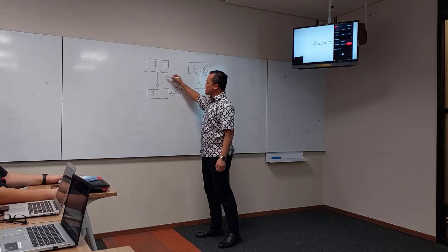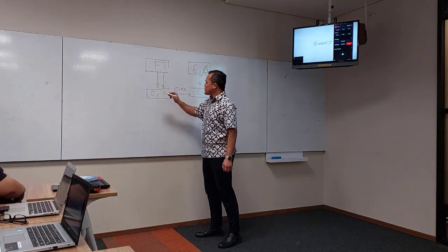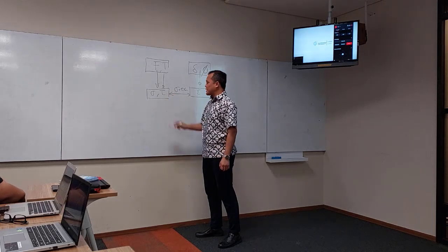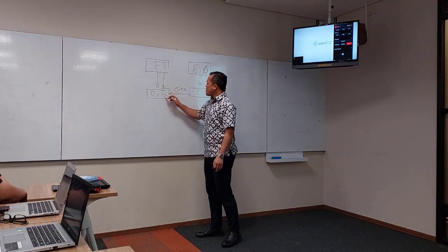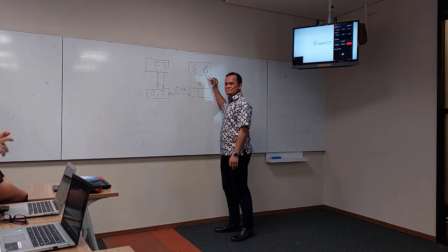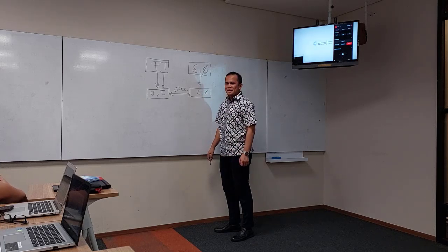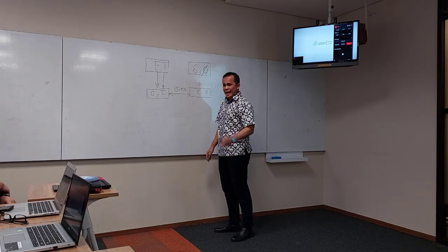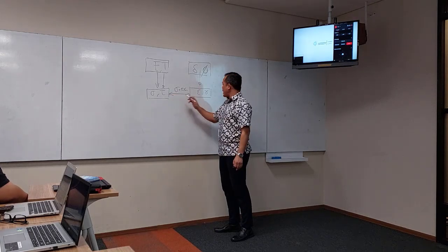Therefore, you convert torsion into stress as well. As a clue, it becomes shear stress, tau. Between tau, this phi also needs to be translated into strain. The strain for torsional movement is gamma, because shearing is gamma. The angle, remember? Okay. So, what relates tau and gamma?